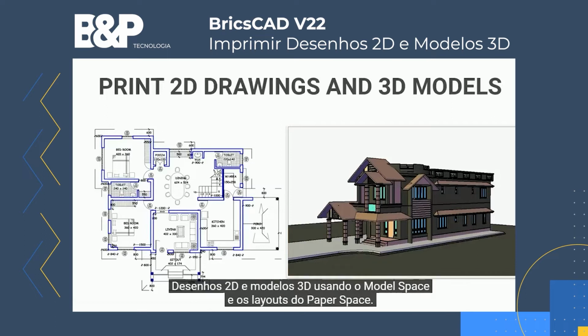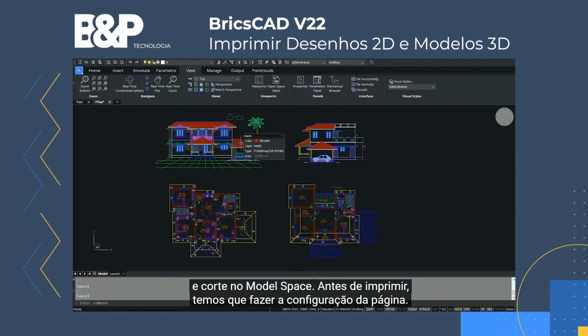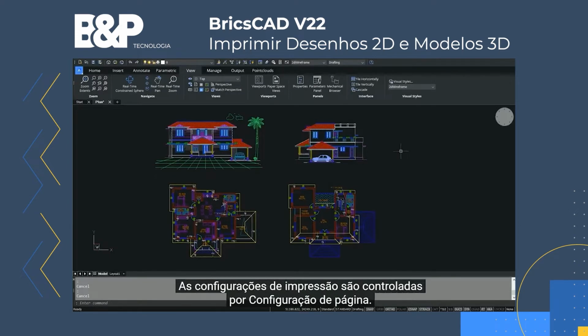In this video, you will see how to print 2D drawings and 3D models using model space and paper space layouts. This is a family house drawing with plans, elevation and section in model space. Before printing, we have to do page setup. Print settings are controlled by page setup.